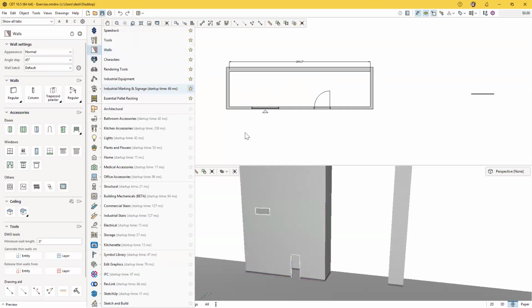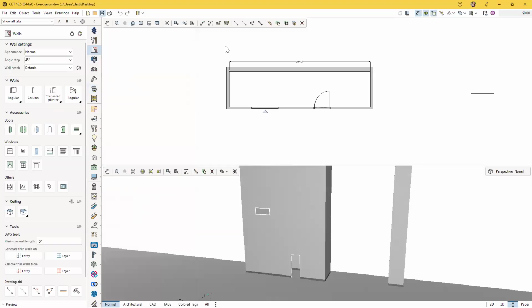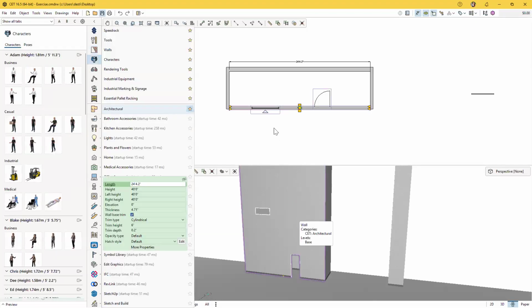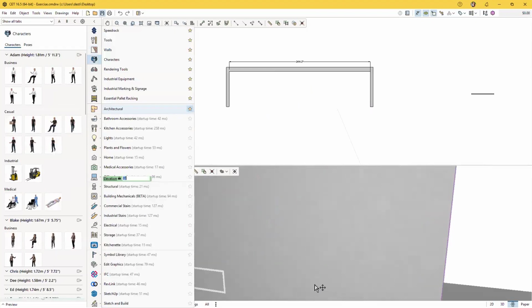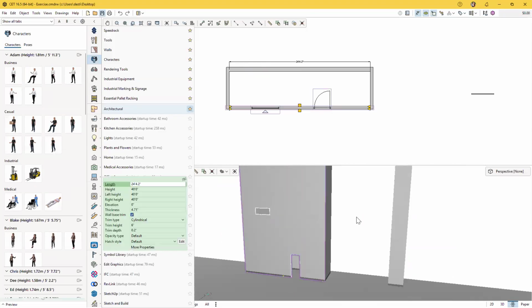If for some reason you really need to be able to adjust your walls or architecture items while you have another extension active, which it does happen occasionally, this lockbox right here, if you unlock it, that will allow you to make adjustments to your walls and things while you are not on that current wall tab.